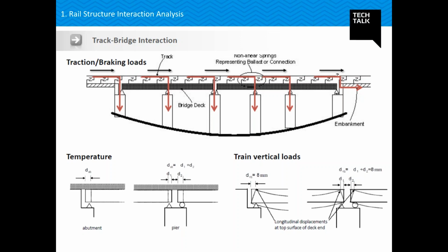Now, if we imagine a third case where another beam is placed over the beam and this whole system is supported by two supports. Now, if I apply a UDL, the transfer of load from the rail to my deck slab and from the deck slab to the support will be a combination of compression as well as bending of both rail and deck. So that is the reason why we need to do an interaction check between the rail and the deck for vertical loads as well.